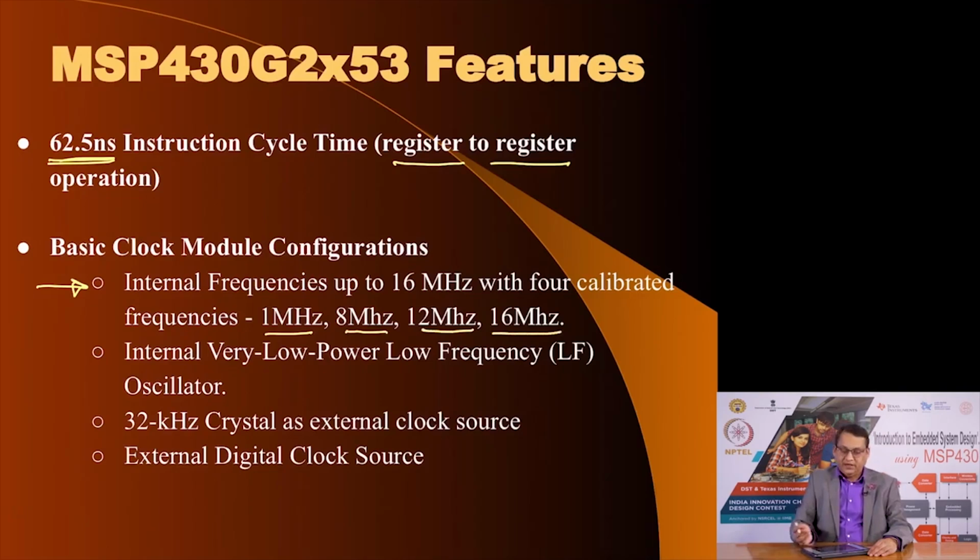It also has an internal very low frequency oscillator up to 12 kilohertz, and this is a very small frequency, and in case you do not have much computational activity to perform, you could switch yourself into low frequency, which will reduce your power dissipation. You can use an external 32 kilohertz, 32 is exactly the 32768 hertz that I had mentioned.